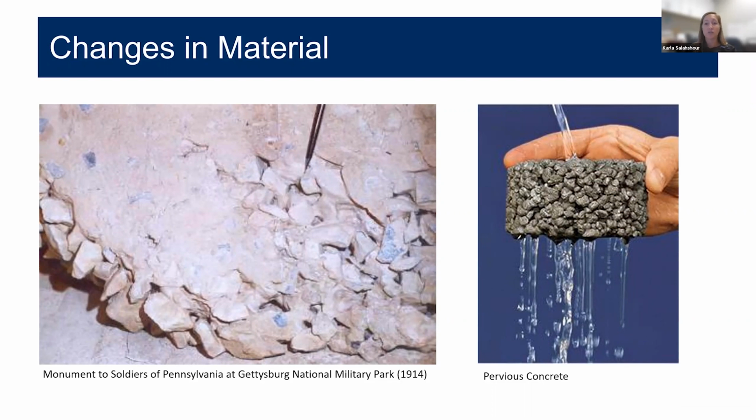And that this mixture was actually quite freeze-thaw durable because it contained all of this void space to accommodate the expansion from liquid water to frozen ice. And historically, Portland cement cost a lot more than the labor. So the concrete mixes historically have decreased the amount of Portland cement, and we increased water content.